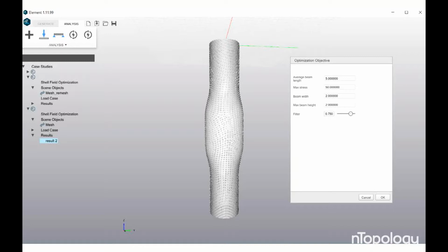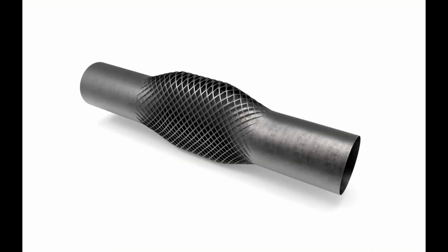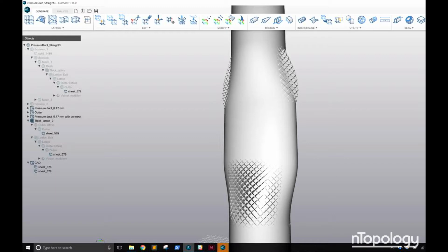Then we can also create more optimal structures, optimal direction, optimal thickness for ribs. And this is one of the final parts. Now, again, with these ribs, you might want to take into account mechanical features, right? So in this case, instead of having ribs throughout the whole part, maybe only on the upskins you want to have ribs. That's another change in the graph: instead of having my modifier be the distance to the two edges, you can have the modifier be the angle of the surface.